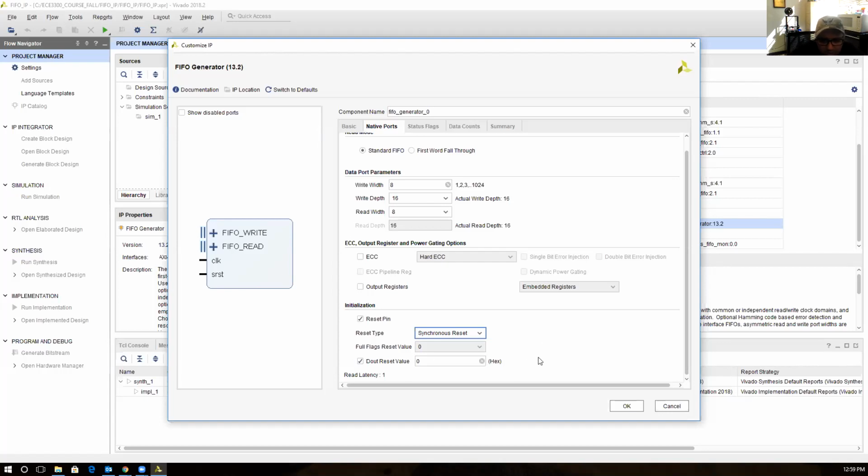Then the dout text, don't worry. Did you see this? Latency, this is the thing that we learned about pipeline, right? Latency 1 cycle. Latency 1. You know what it means? That means that every cycle the output will be reported. Everybody understand what I'm saying? Every cycle the output will be reported.